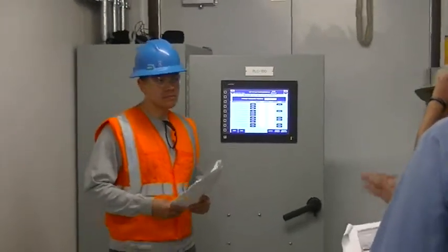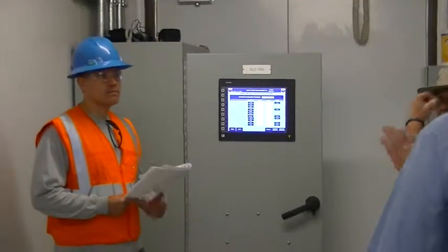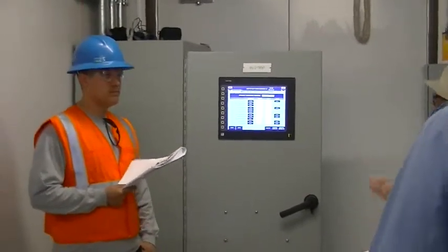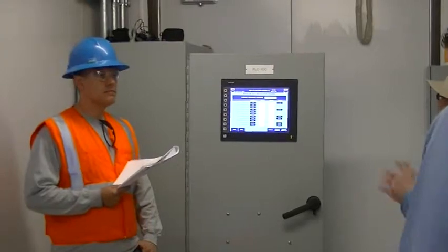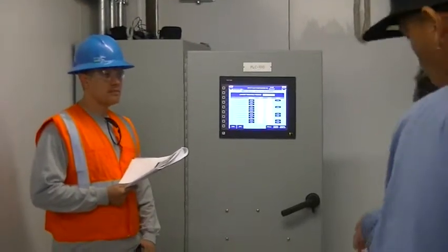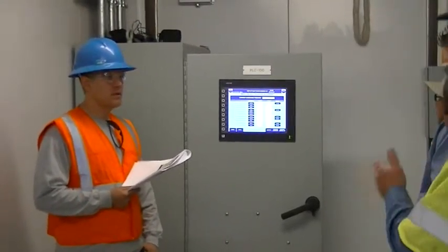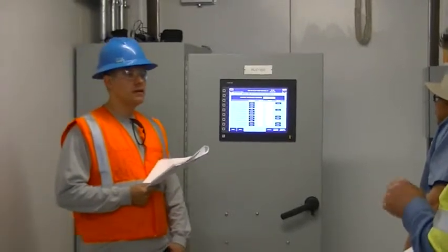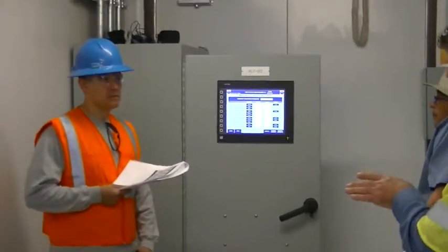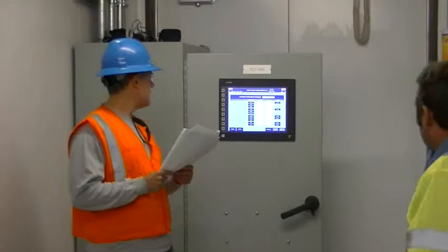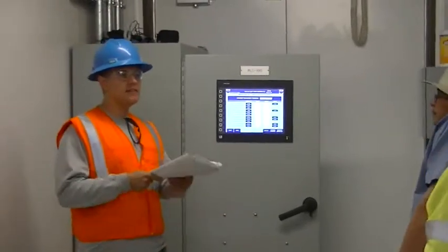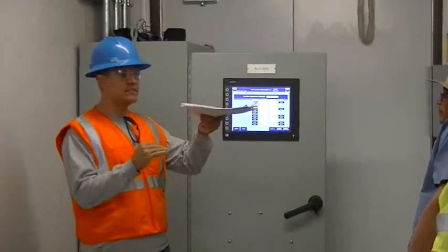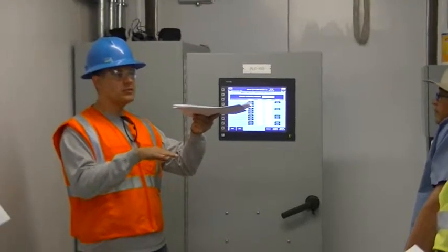Okay, so your lead pump comes on at 60. It can't keep up because of demand or whatever. Yep. And it has to drop 3 psi within 60 seconds or so. Yeah, basically, it has to be below the 65 PSI. That's your deadband. So you have your 65, so it'd have to be like at 62. Right.